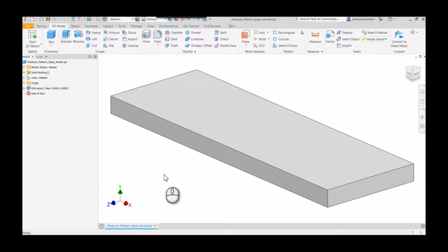of a board. It's not necessarily going to be very good for assembly feature patterning because it won't treat the iFeature pattern as a feature pattern. So if you had 10 holes and you wanted to populate each one of those holes with a fastener, it doesn't do that in the Inventor assembly. So this is a little bit better suited for machining. But if you did want to use it in an assembly, you could always link parameters and things like that.